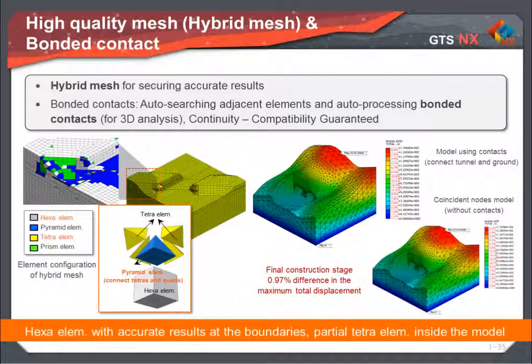Additionally, the new hybrid meshes, which optimize the use of quadrilateral-based meshes, provide more stable analysis than triangle-based meshes, especially at boundaries like excavated surface. So, the combination of hybrid mesh and contact elements enables us to perform analysis even of very complicated models without failure.